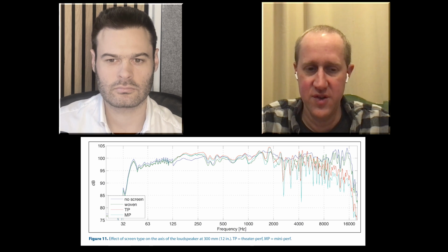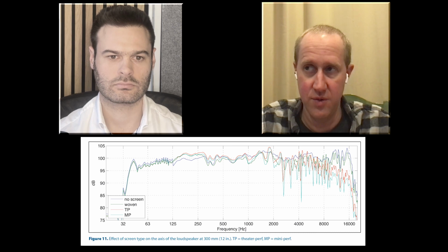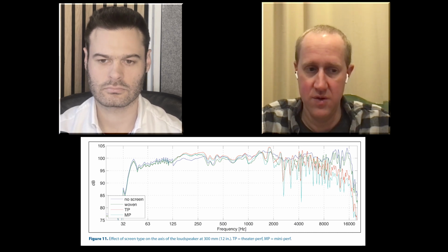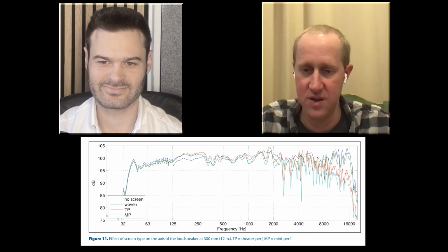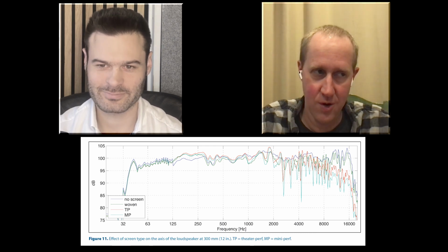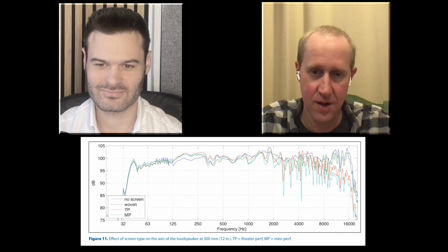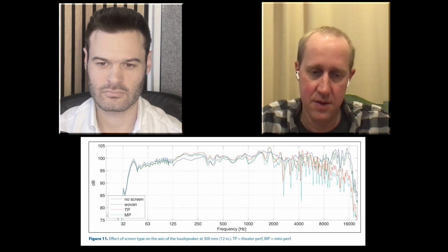Right. So, focusing on 500 and above, that's a range of wavelengths, and certainly you have very short wavelengths in there. So if you have a large horn type speaker, as most theatrical cinema speakers are, with directivity and whatnot, and you put that horn so that it's touching the screen or a minimal distance from the screen, well, what happens? That energy hits the screen, and the energy that's coming back, because it's such a short distance, comes back near full energy, hits the horn at a different angle, comes back out, goes back in, comes back out, et cetera, et cetera. And so when you have that near equal energy, or even 3 dB or even 6 dB down,